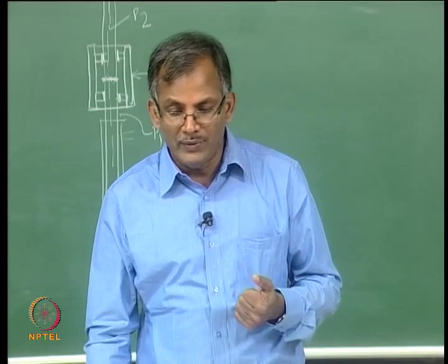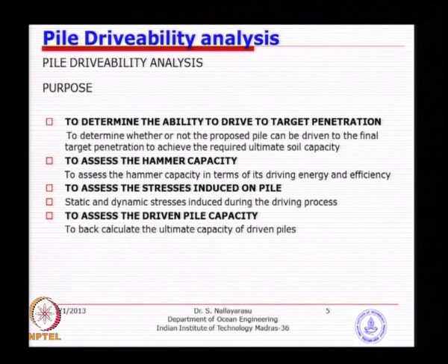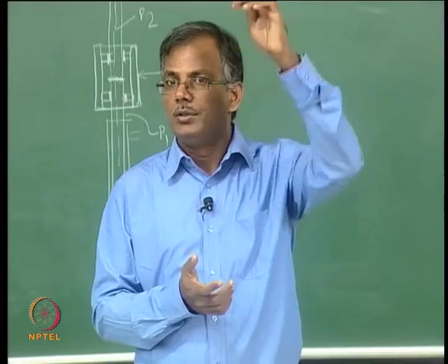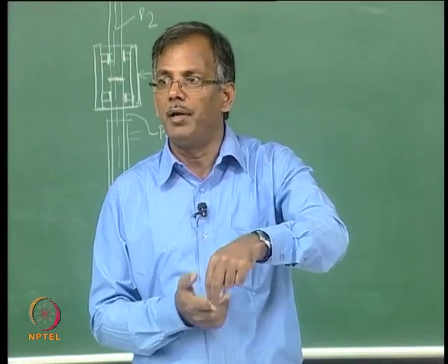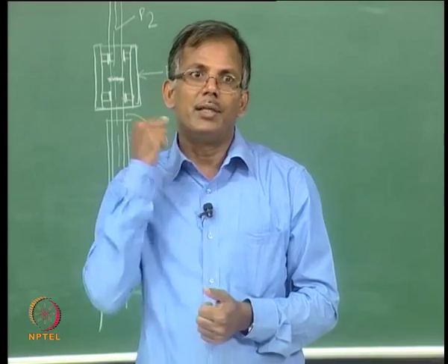That is why, when you are driving, it is obviously better that you make a record of the number of times that you blow the hammer, how much it goes down by each time, and also the stresses on the pile tip. You can place transducers, either displacement transducers or strain gauges, at least at the top of the pile to measure the stresses, which include the incoming stress from the hammer as well as the reflected stress from the soil. So, you can also measure those values.